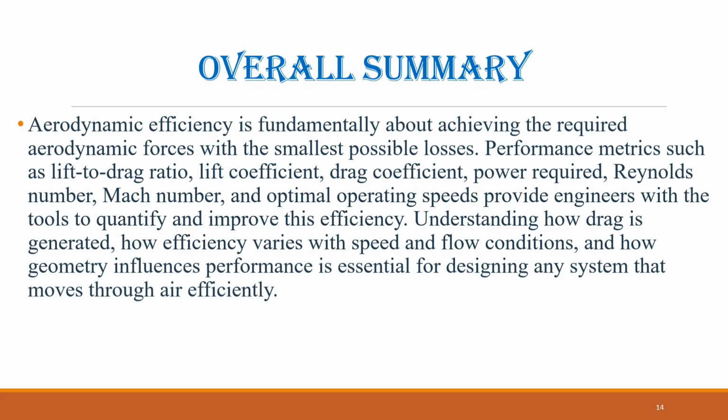Overall summary. Aerodynamic efficiency is fundamentally about achieving the required aerodynamic forces with the smallest possible losses. Performance metrics such as lift-to-drag ratio, lift coefficient, drag coefficient, power required, Reynolds number, Mach number, and optimal operating speeds provide engineers with the tools to quantify and improve this efficiency. Understanding how drag is generated, how efficiency varies with speed and flow conditions, and how geometry influences performance is essential for designing any system that moves through air efficiently.